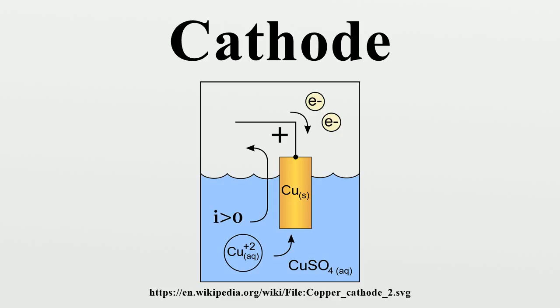In equilibrium, with no applied bias, thermally assisted diffusion of electrons and holes in opposite directions across the depletion layer ensure a zero net current, with electrons flowing from cathode to anode and recombining, and holes flowing from anode to cathode across the junction or depletion layer and recombining.